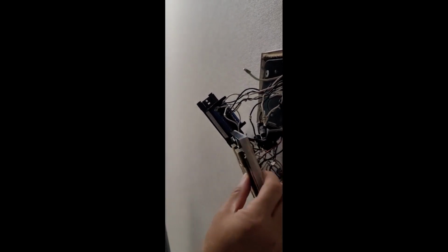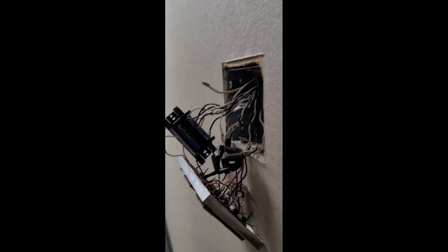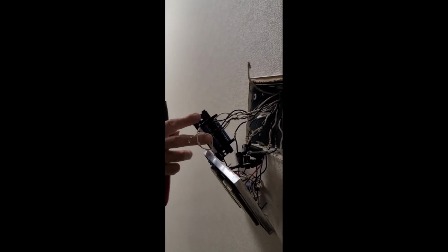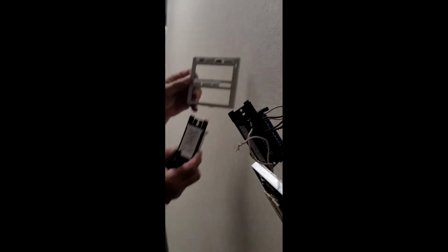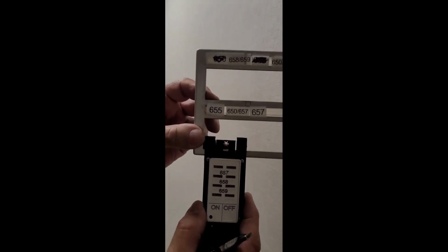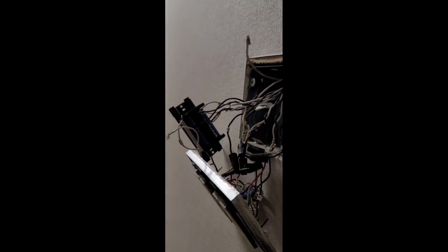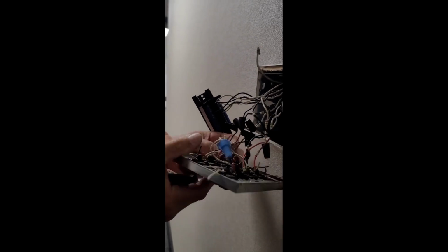Okay, so this one you're gonna film. So first off, you are filming, right? First off, we made sure that we cut off the common. So no switches are powered, so we can't turn anything on and off. Okay. And we double check our plate to match up with our new switch number. In this case, we're going to be doing switch number 657. Old one, the 3rd button over. Now we'll take the wires off the 3rd button over on the bottom. 1, 2, 3. 3rd button over.